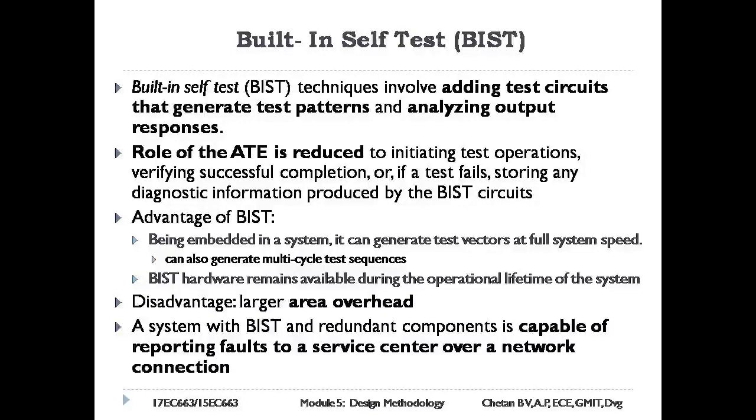Built-in self-test techniques involve adding test circuits that generate test patterns and analyzing output responses. The role of the ATE is reduced to initiating test operations, verifying successful completion, or, if a test fails, storing any diagnostic information produced by the BIST circuits.